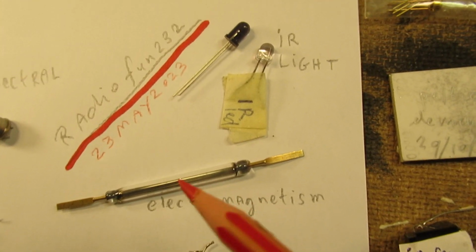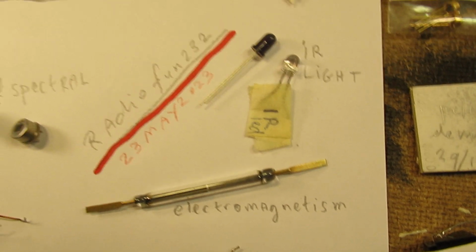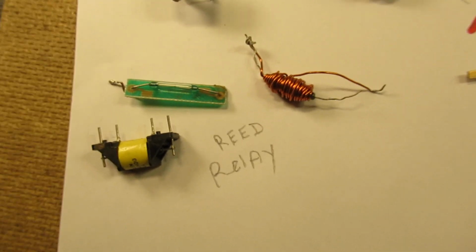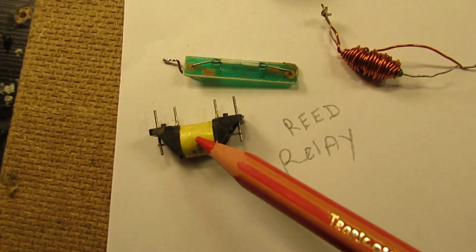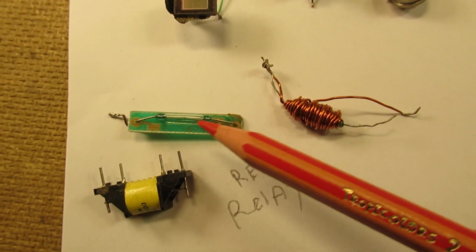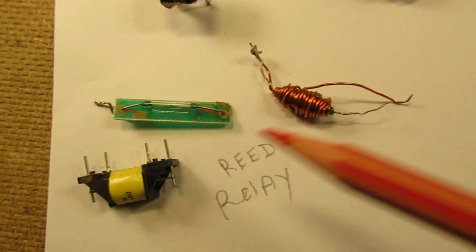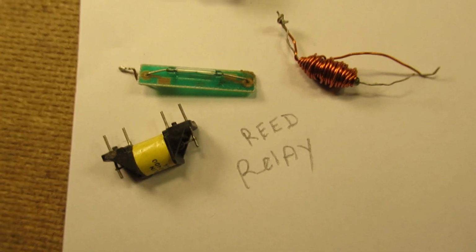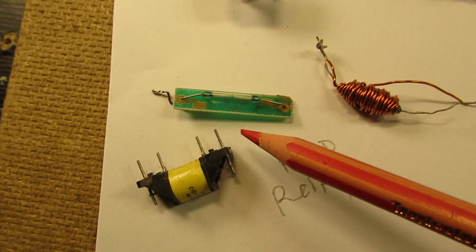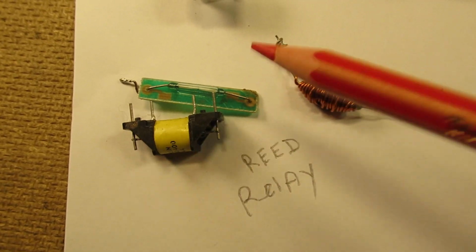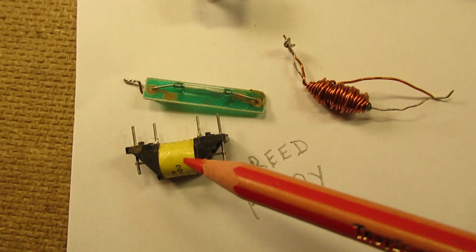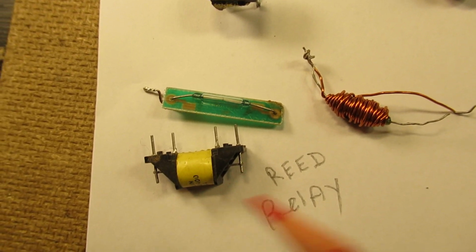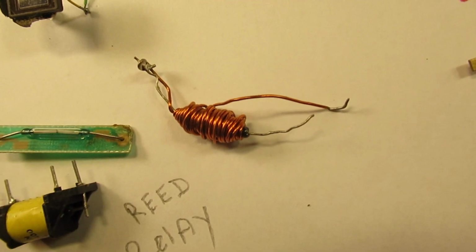Say this is a kind of electromagnetic sensor. It's the classical so-called reed relay. Its working is very simple. There is a coil, you can see it here. There is a glass envelope here with two contacts, and when you send DC through that coil, the contacts make contact due to the magnetic properties of the contacts. So it activates when a current is flowing through the coil, and here you see an experiment that I did.